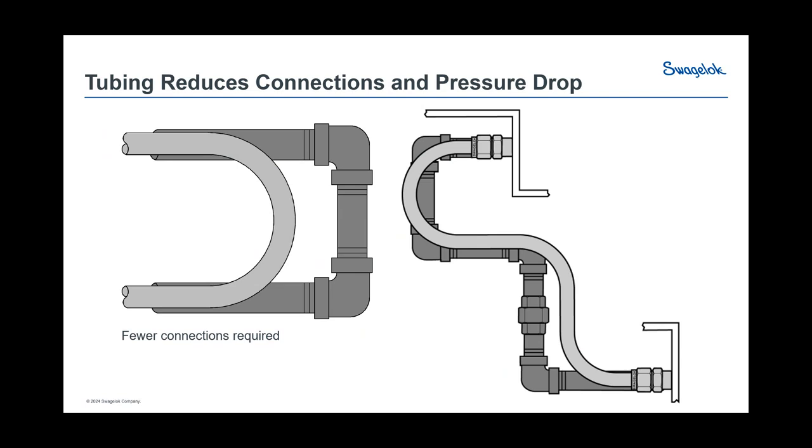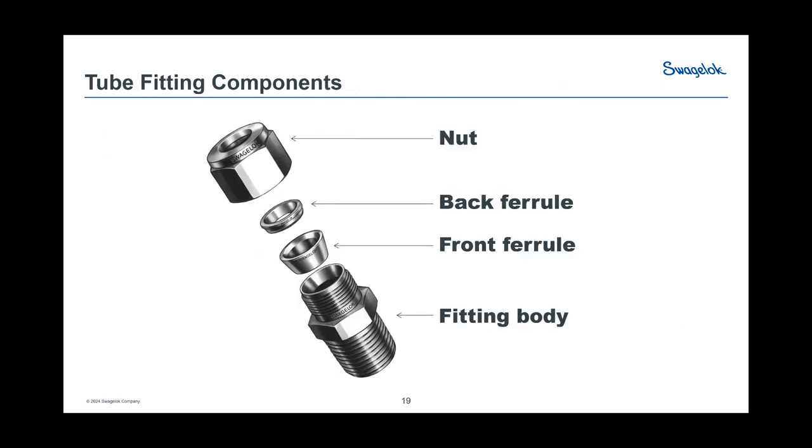The other thing that's important is now you don't have all these threaded joints. Piping connections can be really hard to take apart sometimes. Tube fittings are much easier. So you have 2 tube fittings on the bottom one versus 6 pipe fittings. Many fewer leak points. And pipe threads, when done properly, can seal okay at certain sizes for hydrogen, but it's really not the preferred way. We usually try to stay away from them as much as possible.